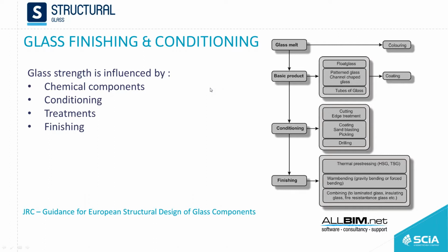This is due to the fact that glass has a thermal treatment that strengthens it, and this will bring some tensions in one of the surfaces. So it's like pretensioning the glass, and that tension gets released when we try to insert an opening. So this is why the production needs to be known, so the production process and what treatments are applied.